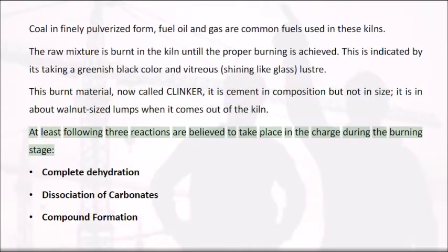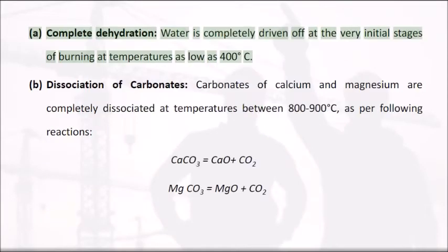At least the following 3 reactions are believed to take place in the charge during the burning stage. Complete dehydration. Dissociation of carbonates. Compound formation. A. Complete dehydration. Water is completely driven off at the very initial stages of burning at temperatures as low as 400 degrees Celsius.